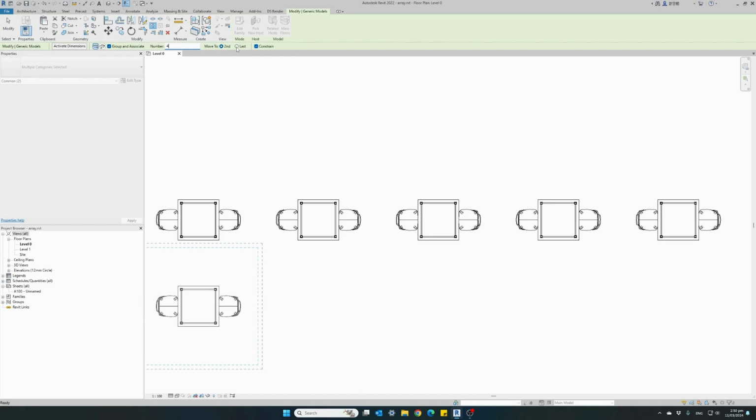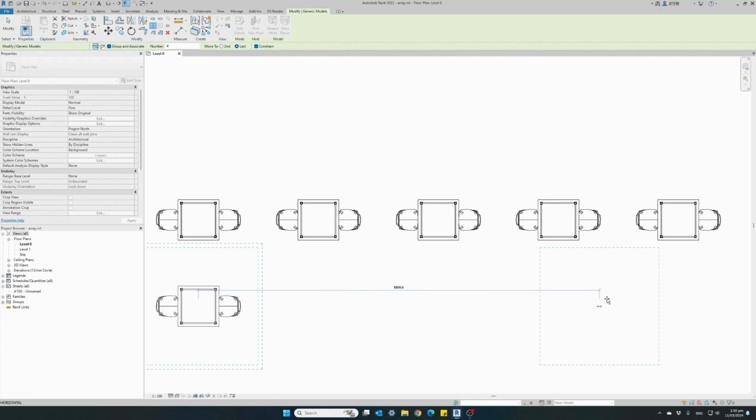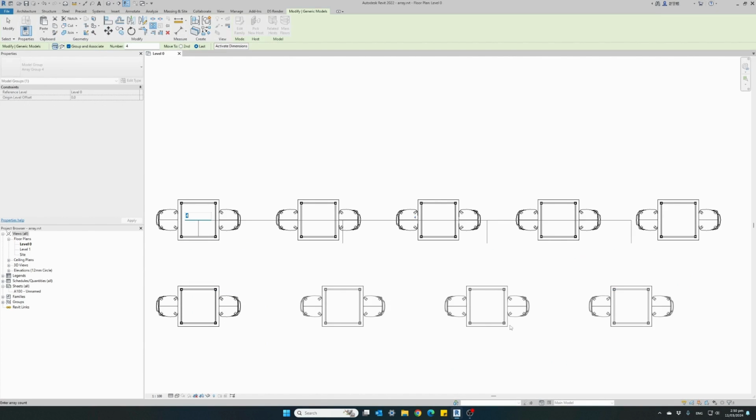I will use the last element position and I want them constrained. With the mouse, I'm choosing the first position and the last. And automatically another 2 elements are created in between the first and the last at equal distances.